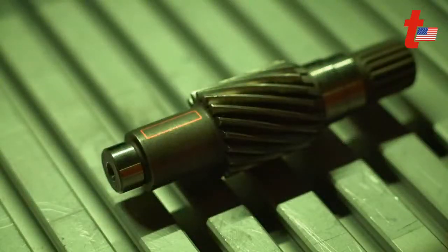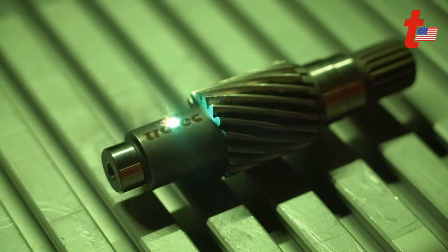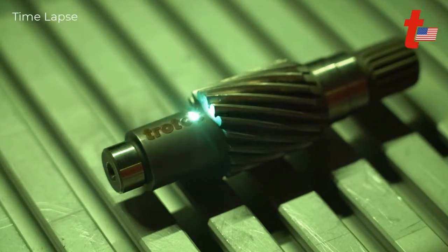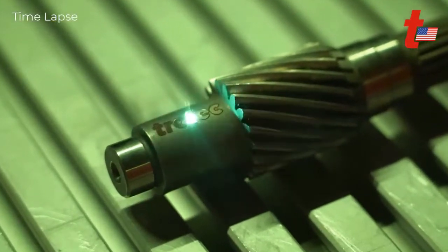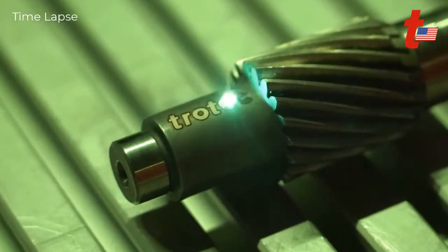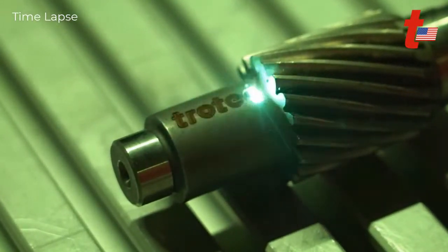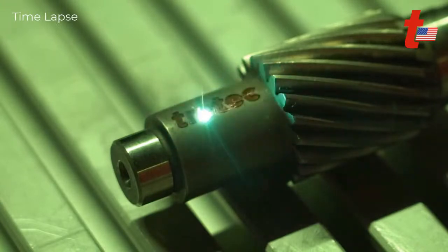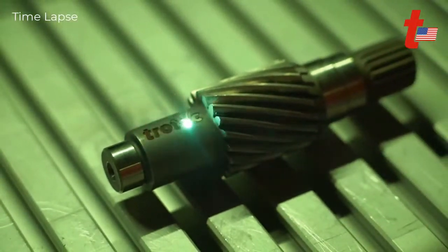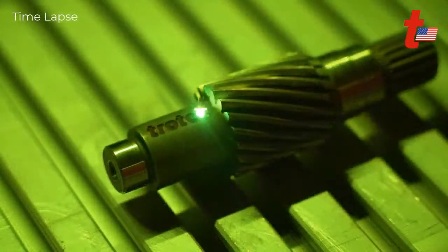And here's an example of this small gear actually engraving with depth. This is live right here, and then I'm going to do a time lapse of multiple passes. I think I hit this one with 20 or 30 passes, and that was one pass right there, and then we do a cleanup. As it turns white, that is a cleanup pass, and that cleanup pass basically removes any of the excess debris, carbon, slag that is left over from each pass. Also, I changed the angle 15 to 20 degrees per pass, so we get a different angle per pass.